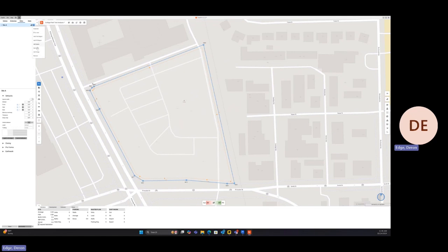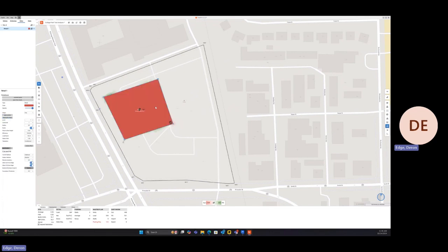So there's a bunch of ways to approach this. Right now, all we're going to do is just create a series of masses. This first mass will be a retail base, kind of a grocery mass. We're going to draw an outline. Inside TestFit it is called retail, but we're going to be classifying it as grocery for our use here. So that's that part.